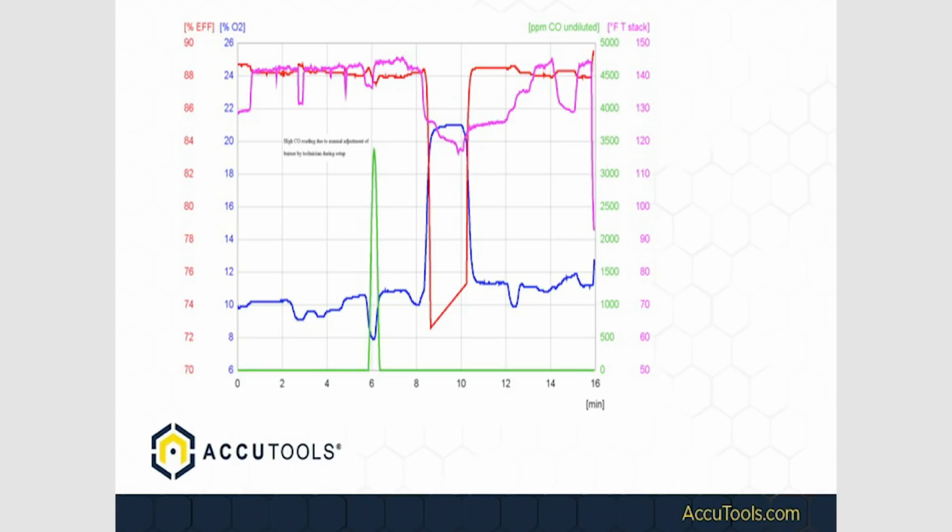This is actually from an elevator. Right? What was happening is every time the elevator would go up or go down, it was creating a plunger effect on the building because they had gone and taped off part of the elevator shaft that was the ventilation for the shaft. So when the elevator would go up, it would depressurize the room when the elevator would go down. And what you're looking at is the elevator going up and down a couple stories versus the elevator going to the 6th floor. The reason we saw this is because we were graphing it on a combustion analyzer and we're going, what in the heck is going on? And I'm listening and hearing the elevator going up and down, and sure as heck, that's what was depressurizing the space.